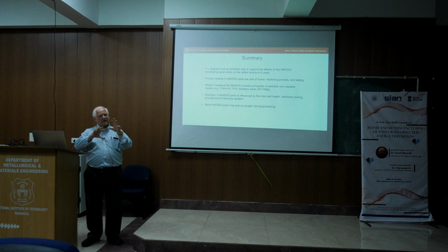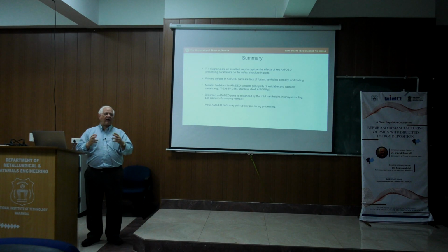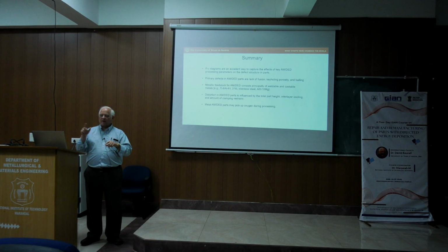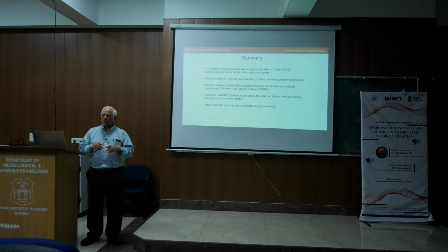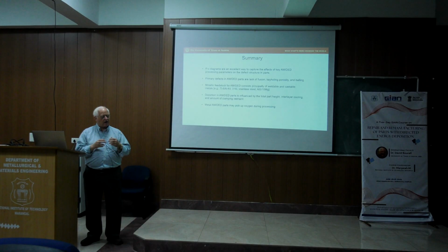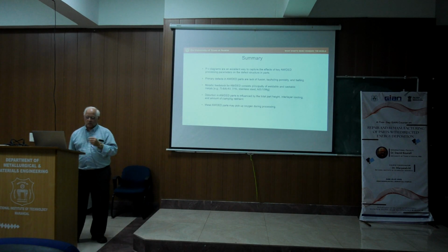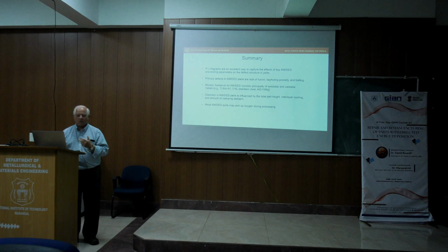Effectively, it orients us fairly well to what the defect structure is, and if we're producing parts with those defects, it gives guidance in terms of, do I need to speed up or slow down? Do I need more power or less power? Those are very helpful when trying to produce high quality parts. So these PV diagrams really are quite helpful in that regard.